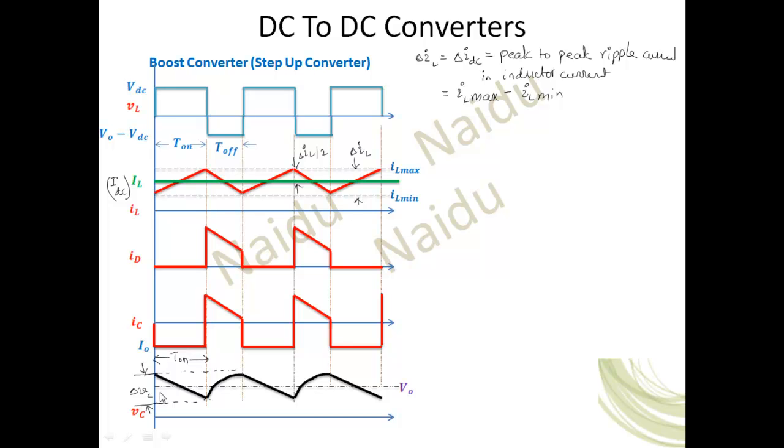So in that case, to calculate this one, we require the area under this curve. Okay, we'll discuss that. This area under this curve is important. Now, first thing we discuss about is delta L, which we need to calculate, that decides how much inductance value we require.